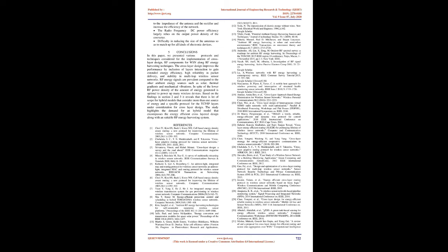Iwata et al. 2016 proposed an antenna with large impedance with gate control diode optimized for RF energy harvesting. The rectification efficiency of 15% was achieved because of discarding the parasitic capacitance, CJ, of the diode with an input power of -15 dBm and frequency of 500 MHz.